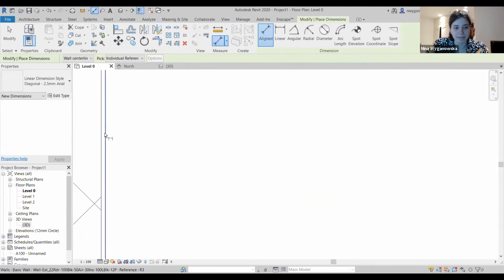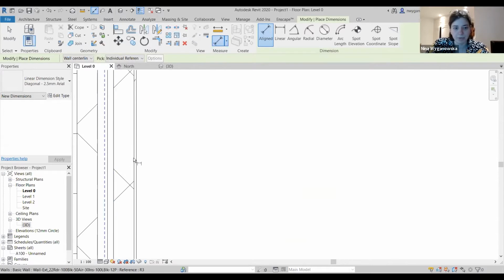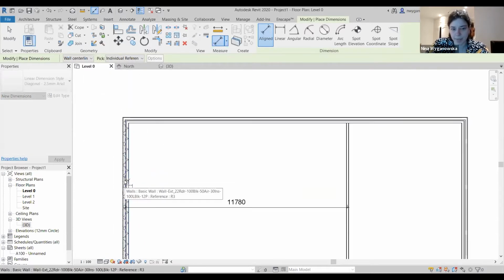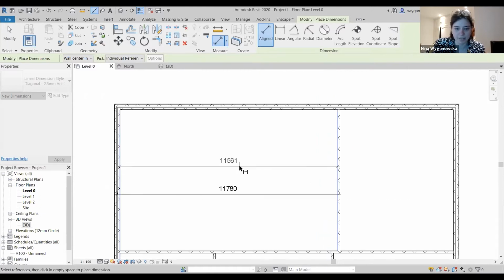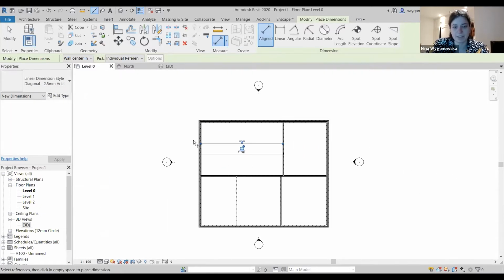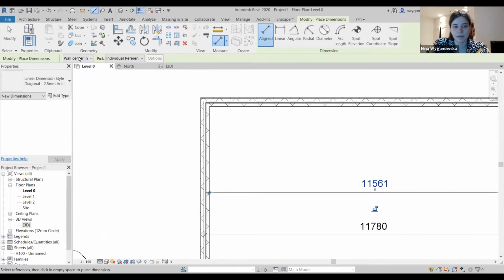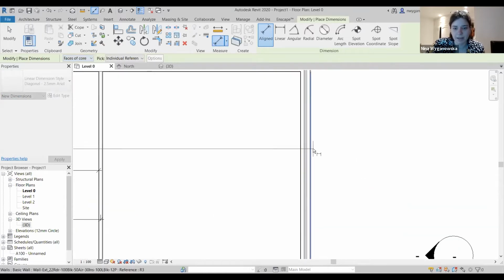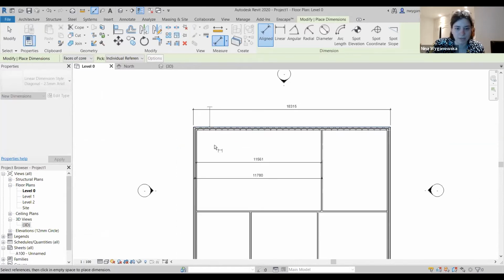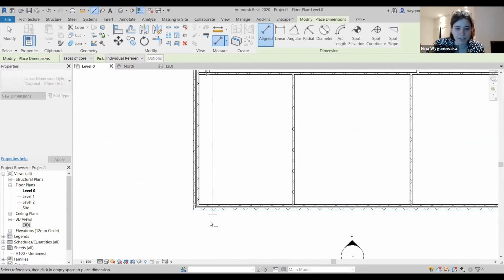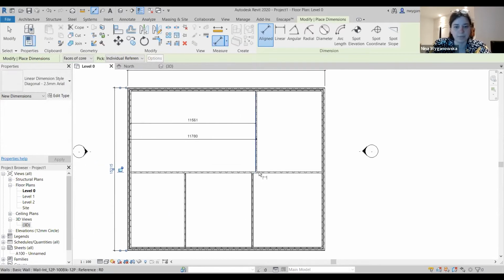you can tab it anytime you want to pick a line within your wall. So you can tab it to make it align with the interior face. And that gives you the dimension, or you can set it out to be the face of anything, which allows you to measure everything. And these measurements stay permanent. You can hide them or you don't have to hide them.